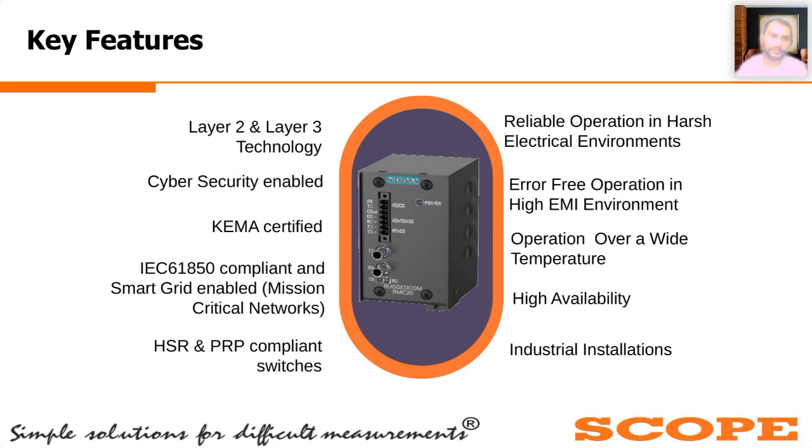Then there is cyber security enabled. These are KEMA certified, IEC 61850 compliant. You can do GOOSE communication through these switches. As I already said, these are HSR and PRP compliant switches, and they are highly available for industrial installations. So these are the key features of the offered Ruggedcom switches.